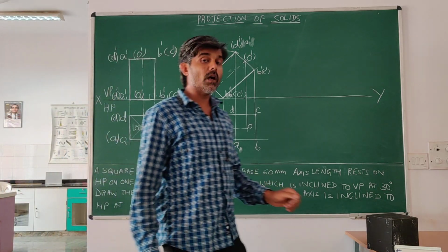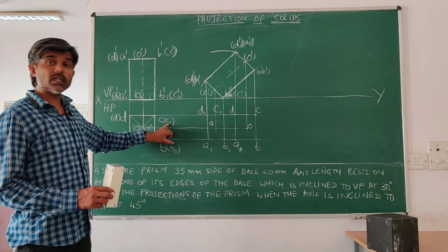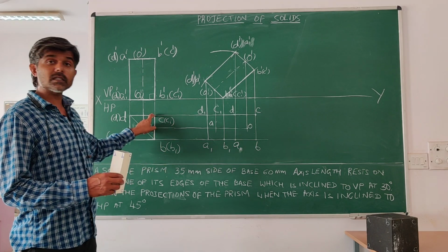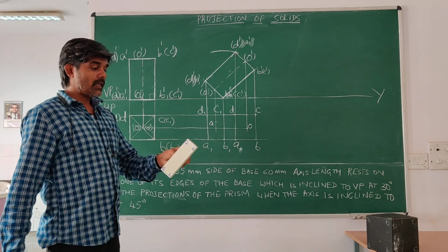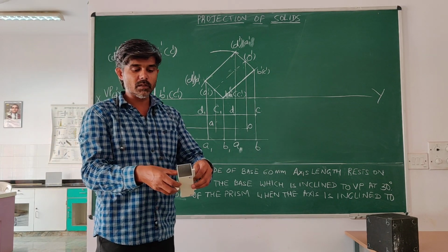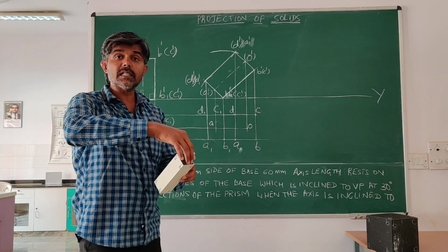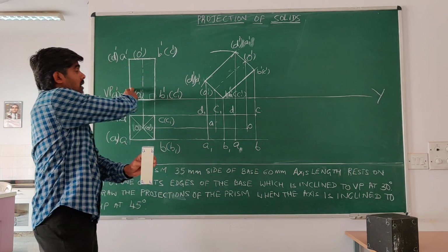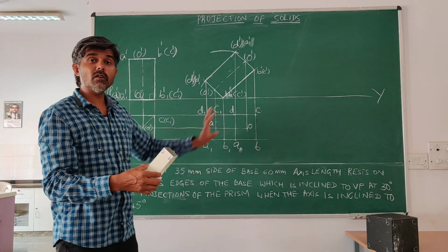Here is the new thing we need to learn in solids. As we have seen here, there are some points which are in brackets and some out of brackets, because we know which are the seen corners and which are the unseen or hidden corners. After rotating this, if the observer sees from the top, I am rotating to make it visible to the observer, so that he can see this face, which was hidden in the first position. These are the changes we need to incorporate.